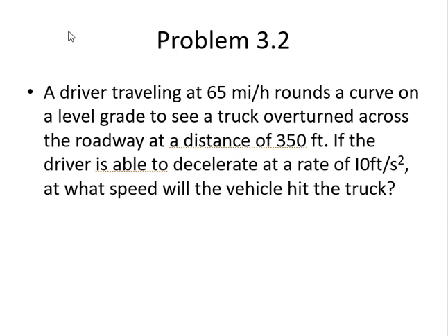A driver traveling at 65 miles per hour comes around a curve, it's a level grade. Now, if the grade is not mentioned and they just use the word level, we will assume it is 0. This is why I said if the grade is not mentioned and only the word level is mentioned, then we will assume 0. If they give you the grade, use it, even if it is 0.1%. Clear?